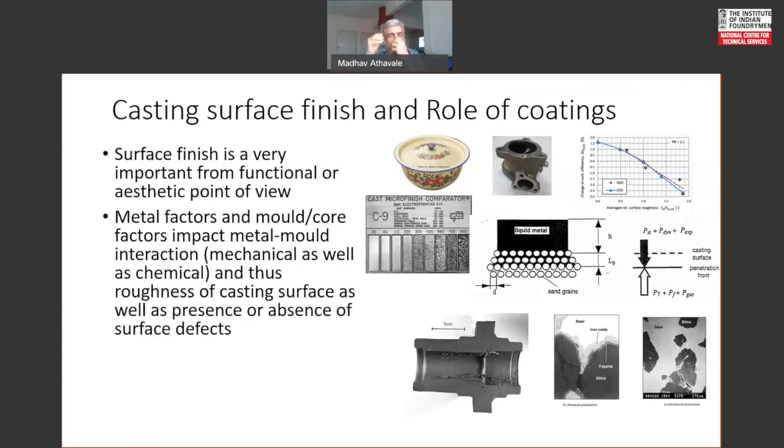Then as the sand layers get exposed to the heat of the metal, the top layer in immediate contact with the metal will initially expand as silica undergoes phase transformations. And beyond 573 degrees, it actually starts contracting. So the top layers will start contracting shortly after they cross that 573, 575 degrees, while the lower layers are expanding.